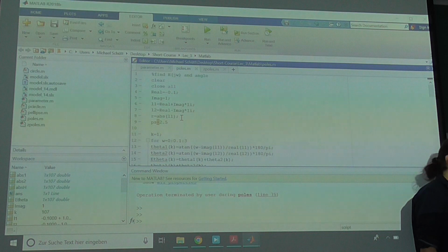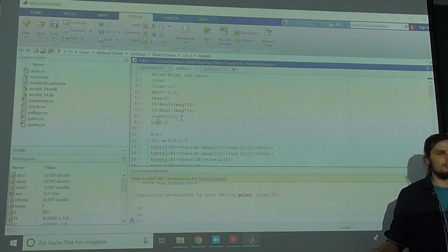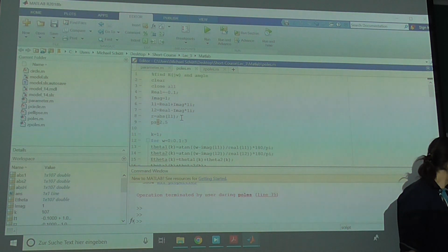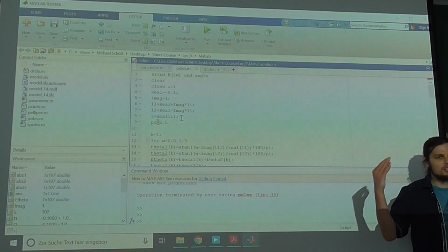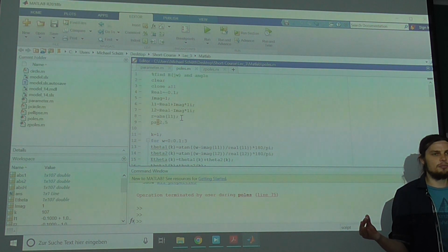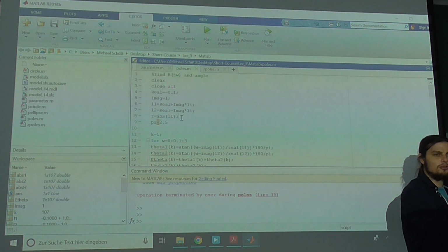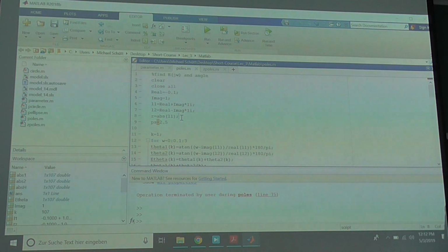However, when you use VDC squared, it is still a linear system, and you can use all the stuff that we taught you. So why don't you just keep it a linear system before you get into trouble, right? So keep it linear, use VDC squared. So in real life, you measure VDC and you just square it. It seems like you do something nonlinear, but actually for your system, that's the state that you need for a linear control. Okay? So that's a very good idea to use VDC squared.